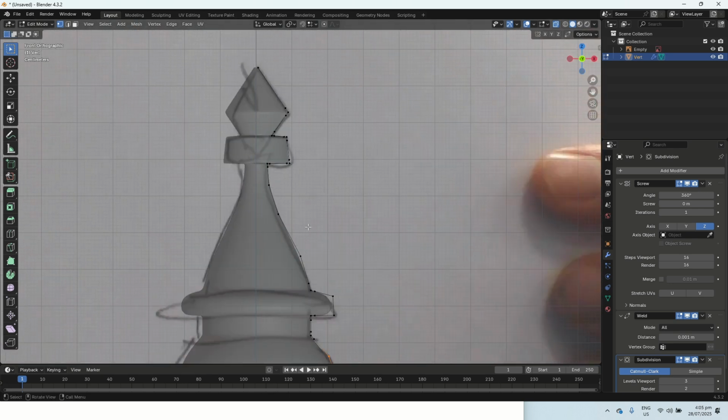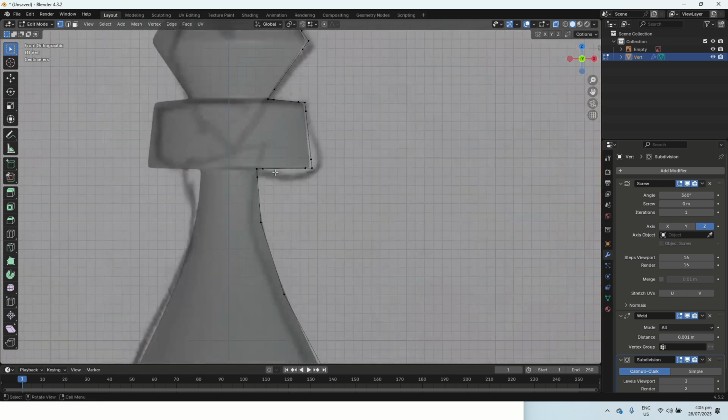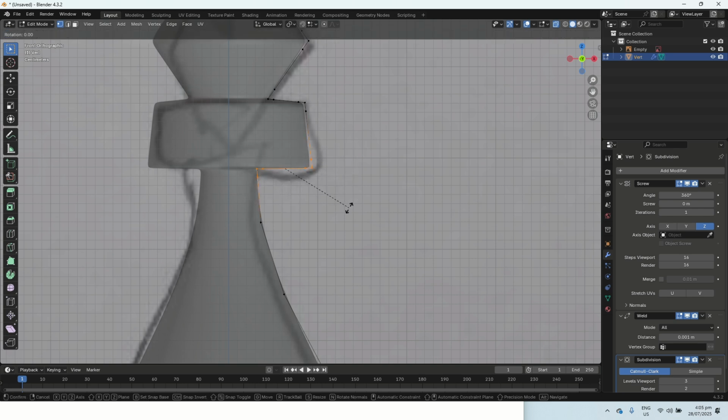All right. One thing I will point out, this large structure I've created here, this almost rectangular shape, that one's not going to print so nice, right? That's going to require that I use supports when I print it. So one easy way to fix that is I can just take this entire area here and push R45, or actually in this case it's R negative 45. So a 45-degree angle like this will print nicely.